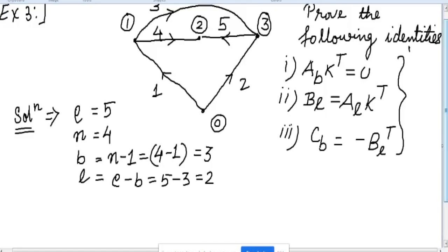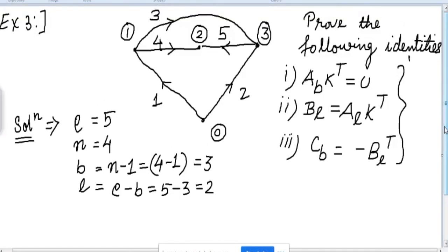We were talking about the branches and the links. As in this problem only the graph is provided to us, they have not asked us to make certain elements branches and the others links. So here we are free to choose the branches and links by our own choice. Then we take the first thumb rule that we have decided. The first thumb rule was, first check whether the first 3 elements can be taken as branches or not.